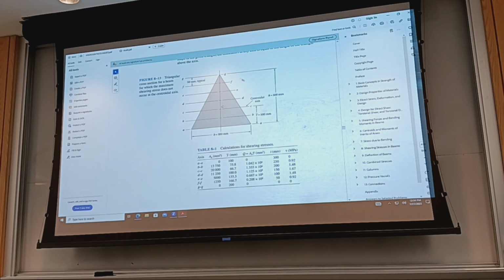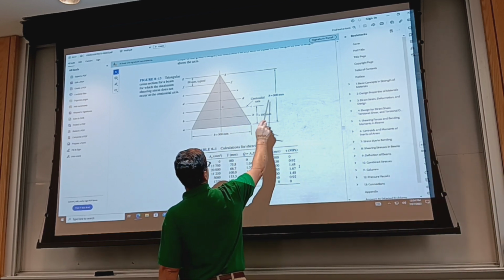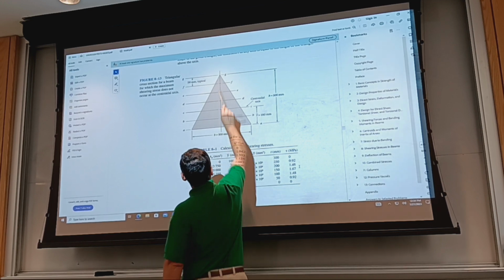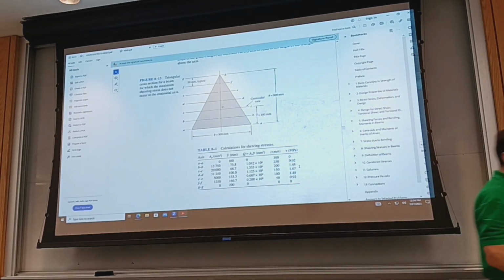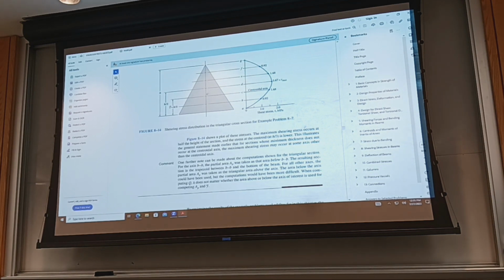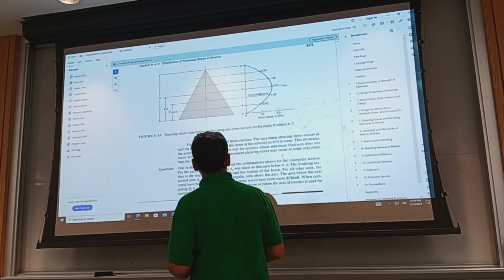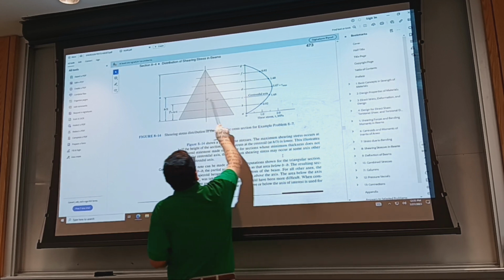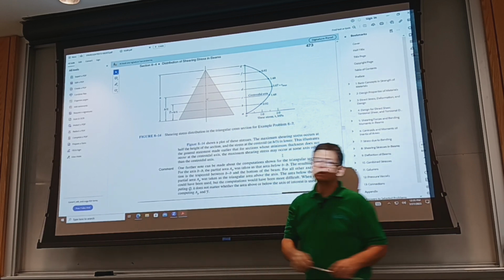If you're to do this for a triangular section, likewise they evaluate what the centroid is for the entire triangle, and that will be what? If this is 300 millimeters, this will be 100. You know this very well. It's one third from the base of the triangle, and then apply the general formula, and the shape of the shear stress as it varies along the vertical is like this one. It does not max at the centroid, it maxes elsewhere, okay? It maxes elsewhere.